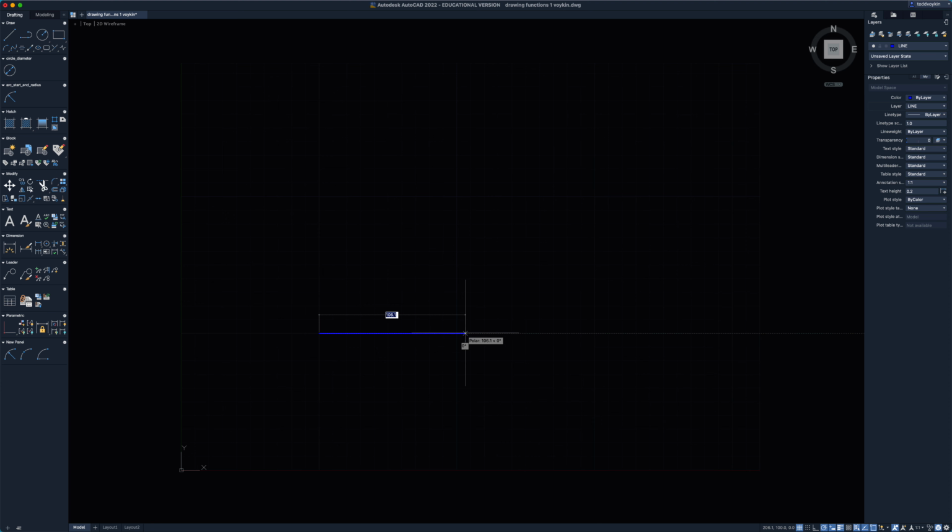I want to move over to the right-hand side and type the length of 150, hit enter, and now I've got this line that is perfectly horizontal and at 150. Now I'm just going to do that again just to show you. See that green line that's right there? That's my snap that's snapping to an angle, and that's this one right down here. It's polar tracking that we set up to 15 degrees. So I want to snap right there where I see that green line, and I'm perfectly at 0 degrees. Okay, so type in 150, hit enter, and we're done.